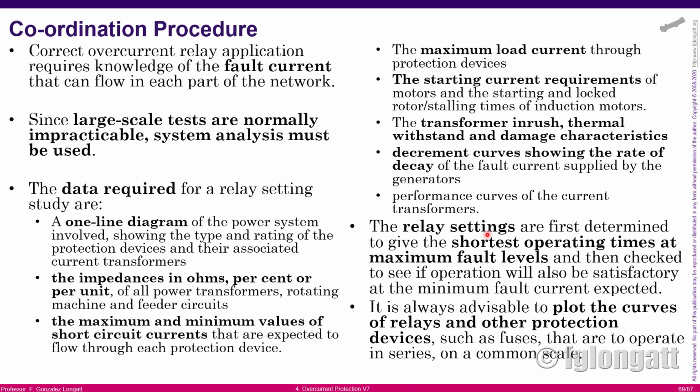If the power system is large, it's a problem, because identifying the condition that will define the short circuit levels is a very important problem. However, today we are using software like PowerFactory that allows automation, and calculating and getting the fault levels for the most critical conditions and any other scenario is extremely simple.